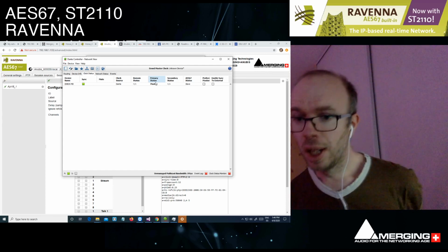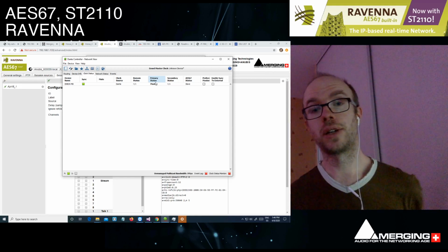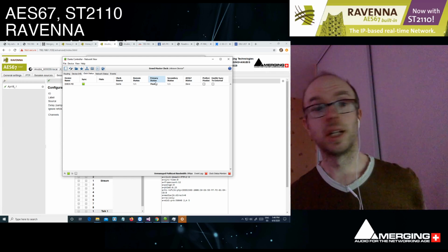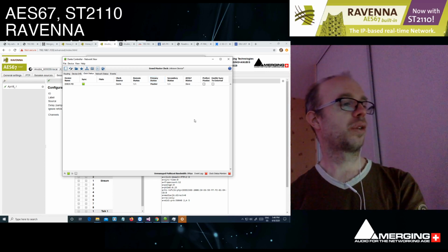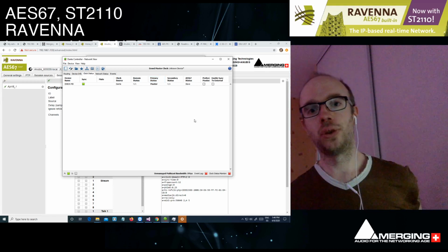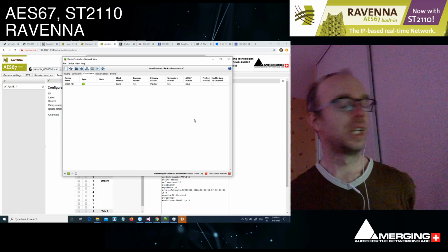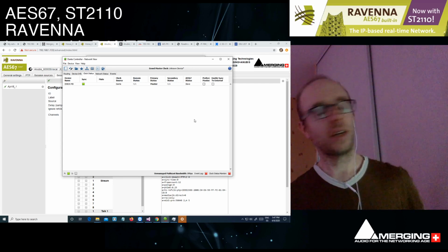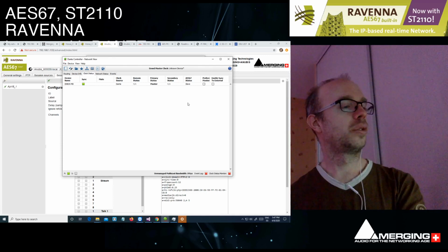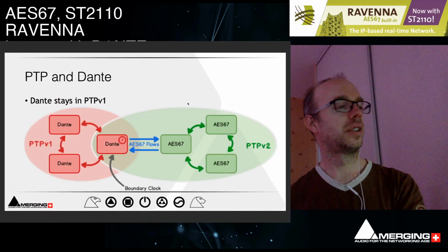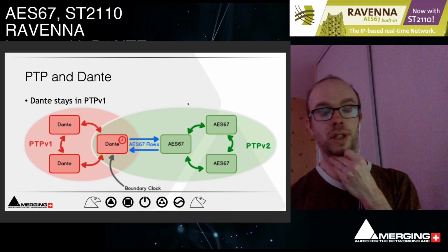So another question from Tibor. Will Dante move to PTP v2? I don't know. I hope so, as a backer of AES67, but it's their own program, and it's actually working great with PTP v1. There are slight differences between v1 and v2, and from what I know, when you're using Dante Domain Manager and you switch those Dante devices to ST 2110 mode, they are using PTP v2 already. So you can see it however you want. You can see it as a way of trying to stick to what's already existing in the lower tier, because Dante Domain Manager is the higher tier, or just as a convenience.